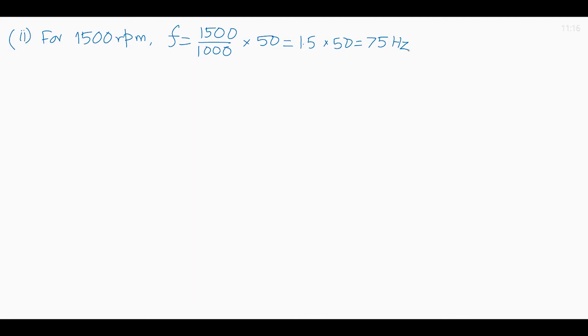So, because frequency is 1.5 times, synchronous reactance XS2 is 75 divided by 50 times the reactance at rated condition, which is 9 ohm. So, it is 13.5 ohm.